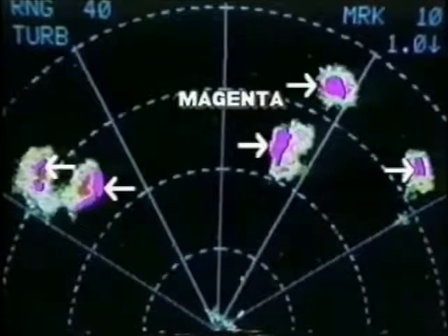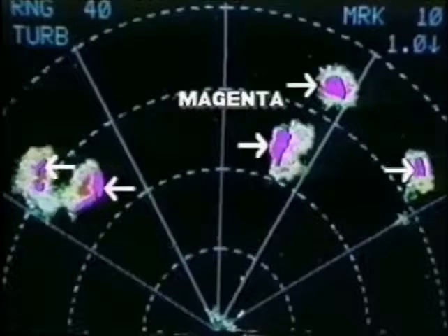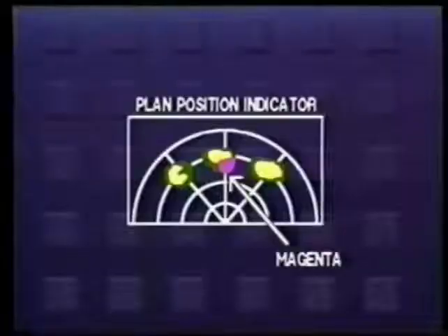Manual gain control can also be used to help evaluate rain cells for the presence of turbulence. The turb display is unaffected by manual gain. By reducing the gain, and therefore reducing the strength of the displayed rain signal, any areas of turbulence will be dramatically highlighted. This tool can be especially useful on EFIS displays which do not provide the magenta color.